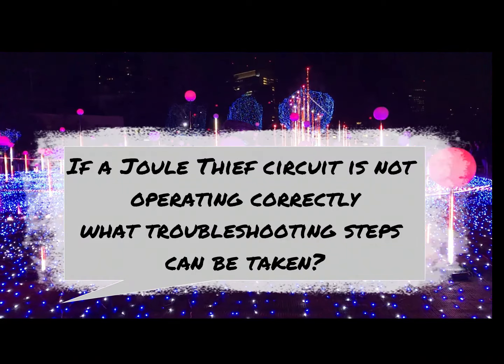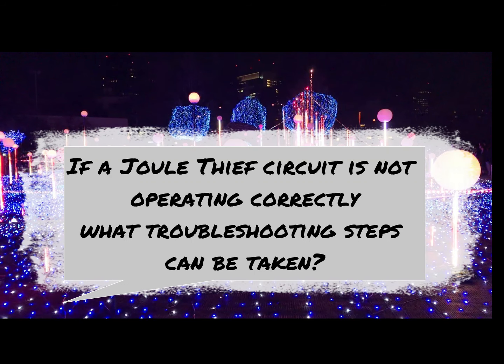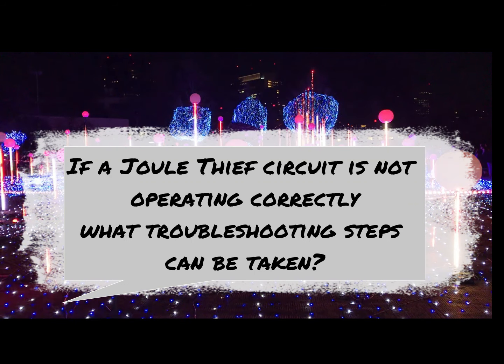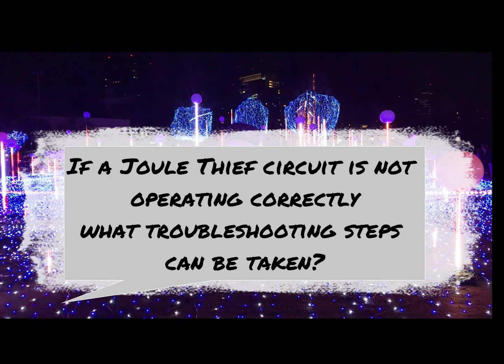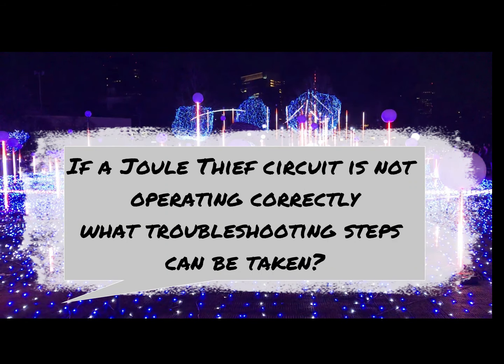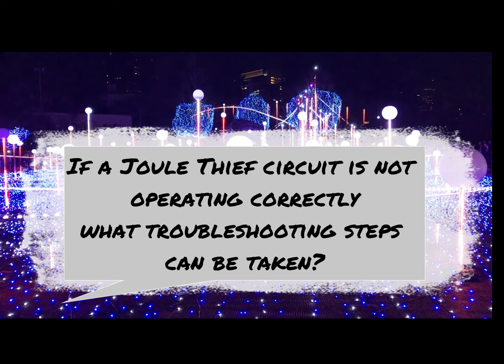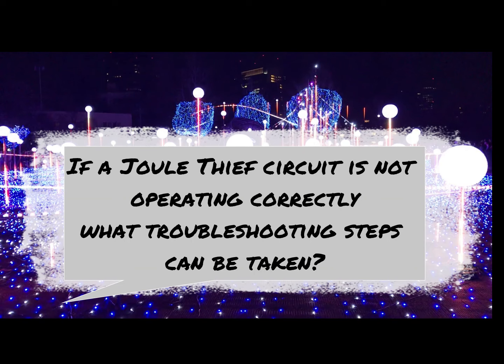Excellent insights. Now, on to the next point of discussion. If a Joule Thief circuit is not operating correctly, what troubleshooting steps can be taken? Of course, to troubleshoot a Joule Thief circuit, you can take the following steps. Check the wiring. Make sure all the components are properly connected, and there are no loose connections or broken wires.